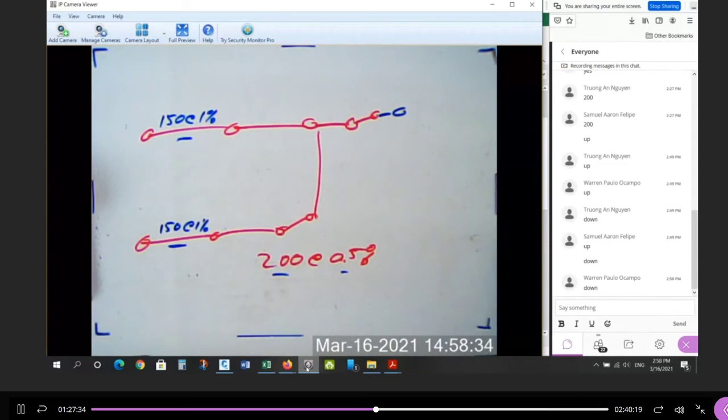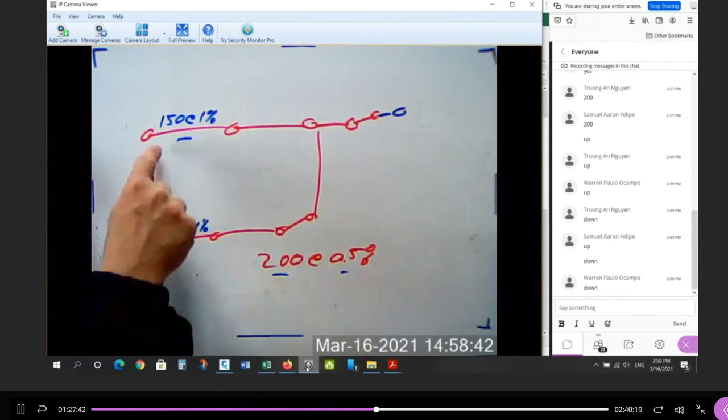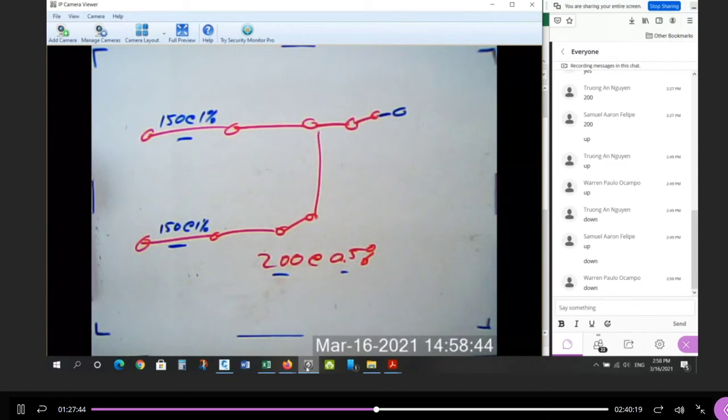For the same reason that we did it in Richmond Hill, it's a requirement in Milton. So I would do that to try and get the scouring velocity at the smallest flow to bump up a little bit, so that we don't have any of that settling issue. Okay, so everybody clear with that? So when you create your spreadsheet, the pipe sizes are all 200 at 0.5%, except these two.